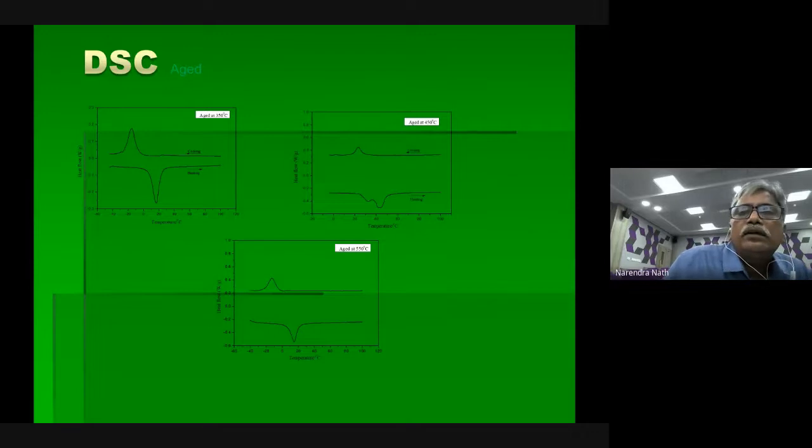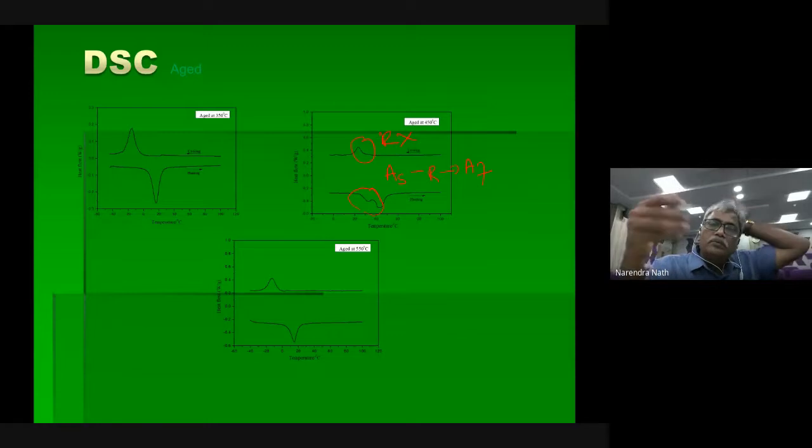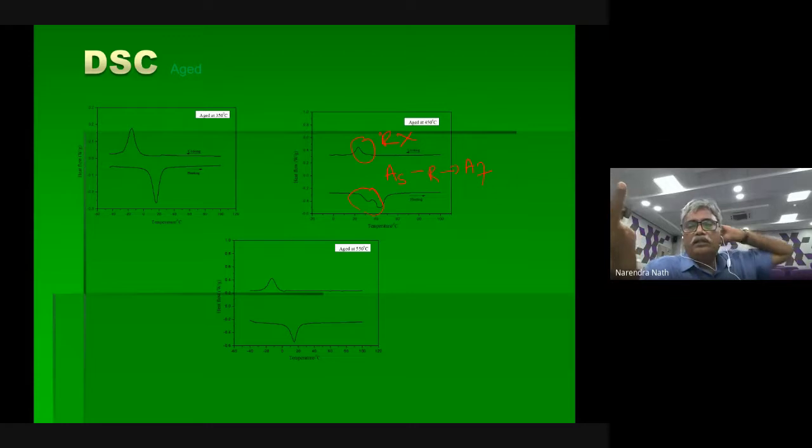And again, the low temperature aged sample you can see. And what I said, rhombohedral phase you can see here. Now it is heating. When it is heating, austenite starts, reaches rhombohedral, then austenite finish. Whereas here there is no R. In some cases, in both cooling and heating, R may appear. It depends on the processing history, the cooling history, and the heat treatment history.